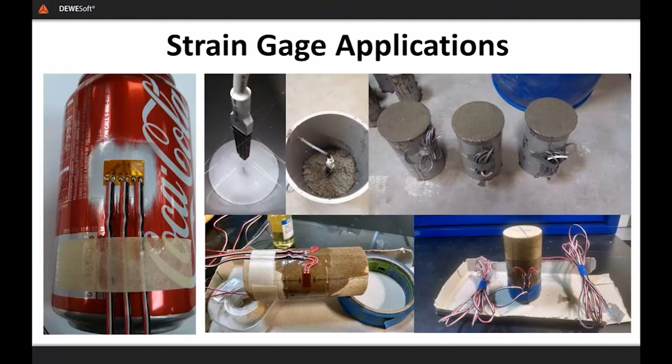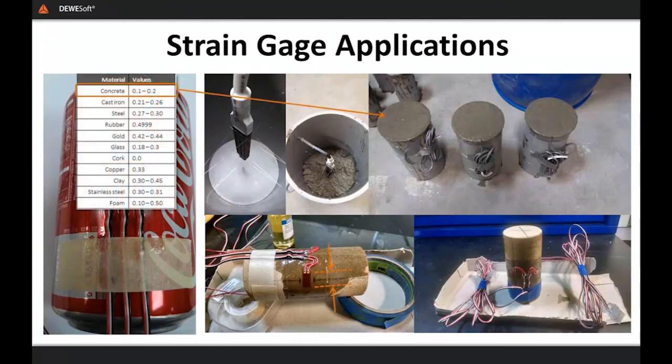You may remember my reference sometime earlier regarding the Poisson component differences. Those unfamiliar with this sort of gauge work will probably notice that some of the gauges are extremely long. This is because of the properties of the material, and it reinforces the aspect of gauge selection in respect of the material that you plan to apply them to. The surface structure and density of concrete is a macro version of aluminum and other alloys, so the gauges grow proportionally in length to the structure.